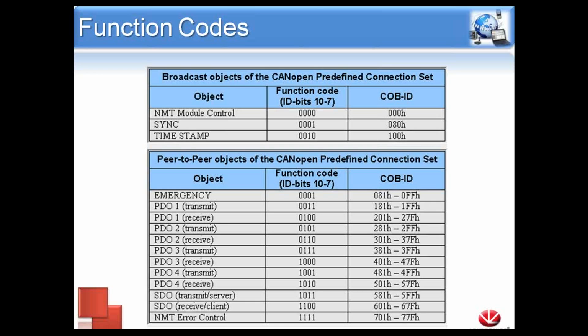All right, so here's a chart breakdown of all the codes we just mentioned, going in order of priority by their COB ID. So of course, the first one, COB ID 0, is changing the state of the machine using NMT. Next, we have the sync. After that, we have a timestamp. It's possible for all the controllers to share a UTC timestamp.